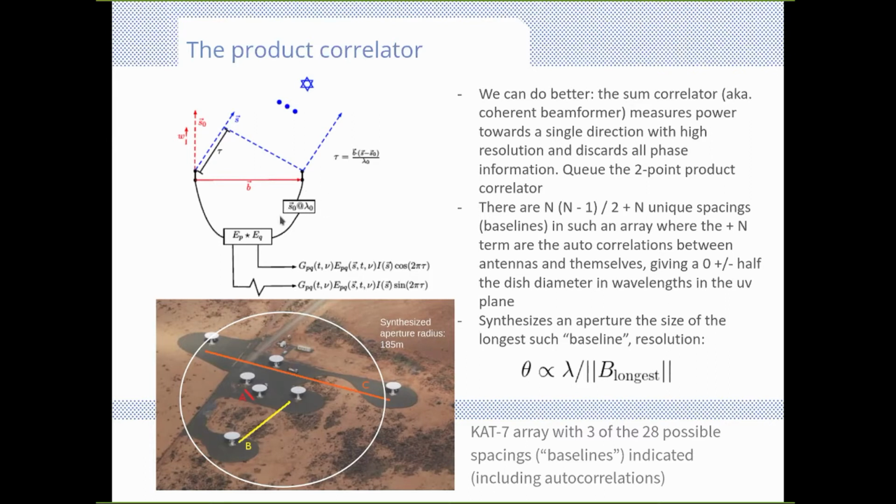Within this interferometer, we again have the phase tracking computer, which steers the interferometer on the sky by injecting a complex exponent. And what we also typically have for such a correlation system is injection of 90 degrees of phase as the output on the system. So we have both a cosine measurement and a sine measurement.